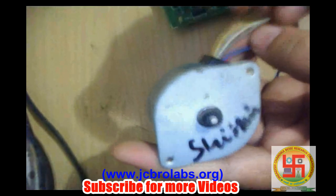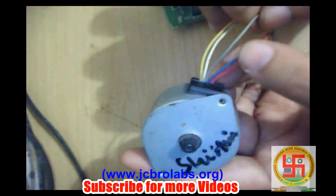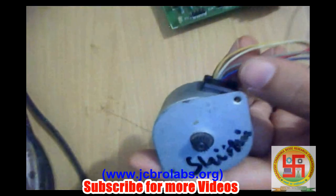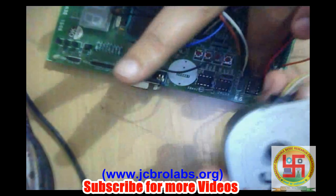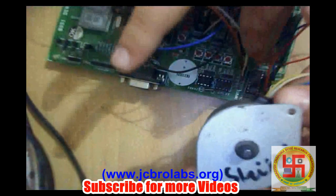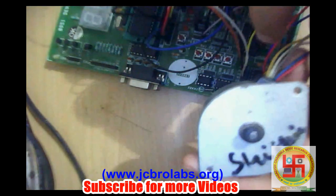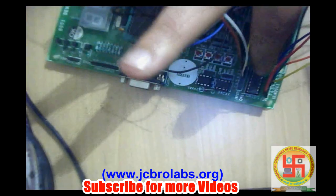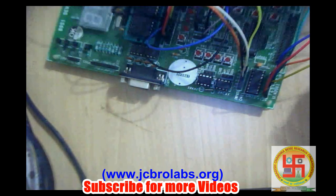There are 2 wires for one winding and 2 other wires for another winding. This middle wire is a common wire, and it is used for providing power supply to this unipolar stepper motor. So for this unipolar stepper motor we need a different kind of driver IC, and here that is ULN2003. This unipolar stepper motor can be driven with the help of this ULN2003 IC. The only thing which needs to be done is to connect this common wire to plus 12 volt or plus 5 volt power supply depending on the requirement, and then the remaining 4 wires can be connected to the ULN2003 output pins, and the input to the ULN2003 IC can come from the microcontroller.